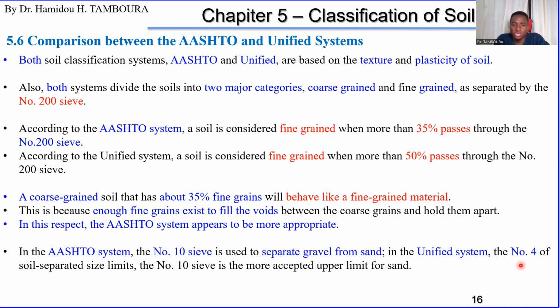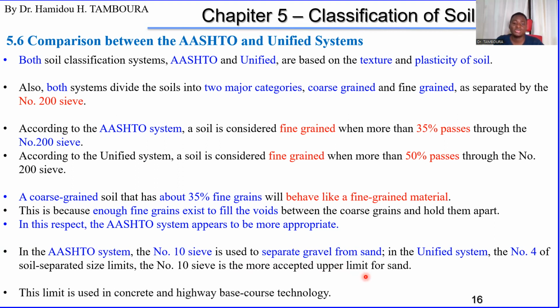Okay, and the number 10 sieve is also more accepted as the upper limit of sand. So this limit is used in concrete and highway-based course technology.